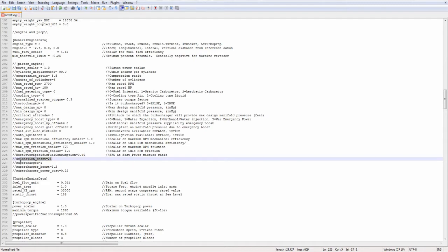So that is where you define the detonation onset. Most add-on planes don't make use of this feature, which is sad. I really wish they would, because it's a way of making sure the end user's flying the plane properly. Now, if you do define a detonation onset, you might want to define an anti-detonation system, especially for race airplanes. We'll talk about that later on in the video.